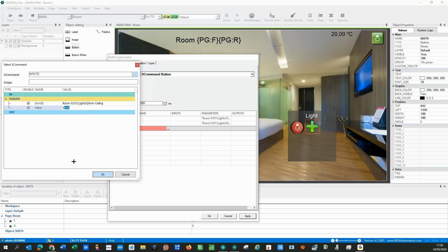So stop dimming, it is the order. When you release the button, you will say stop dimming. So for example, 1000 or 0000, it doesn't matter. It's break. So this is binary, in decimal can be 8 or could be 0 also, doesn't matter, because the important thing is that the last three zeros, the last three bits are 0 in this case for the relative dimming 4-bit codification. So we need to understand this.